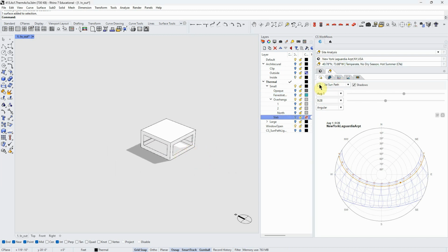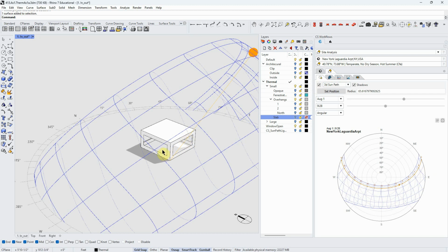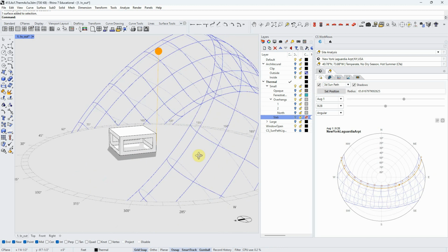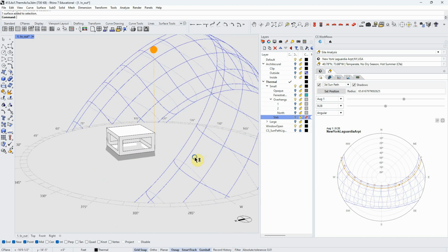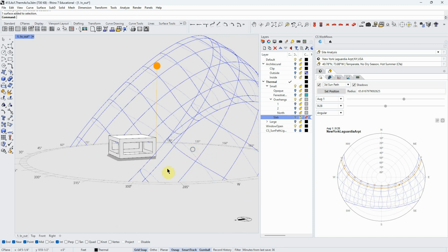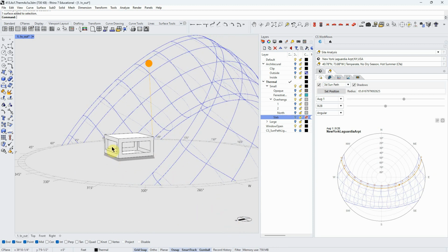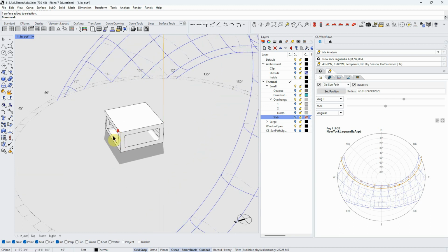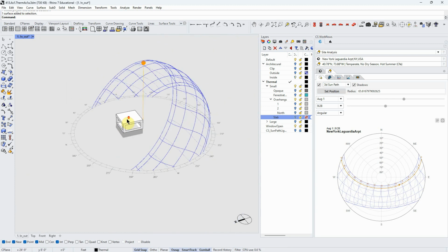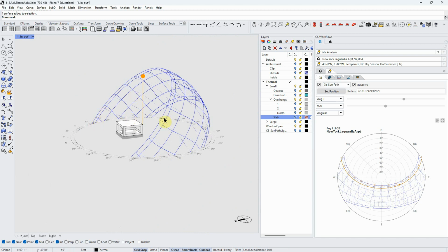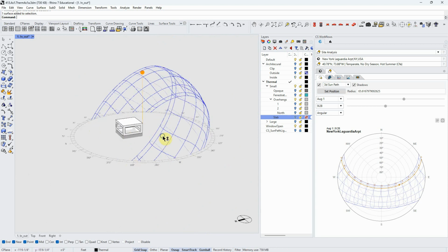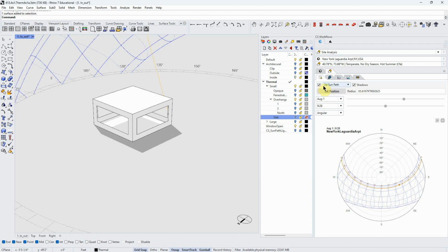One thing we should remember, and always when you're modeling any kind of variables, you need to have a basic, conceptual understanding of what you're modeling. So we need to understand the sun, and we already know that on the north side in New York City, in the northern hemisphere where we are, we're probably not going to get very much, if any, direct sun through the north because of the way that the solar window works. Even in the summer, when we're rising and setting pretty far to the east and west, it's not far enough probably to get any direct gains. Let's see if that's true.